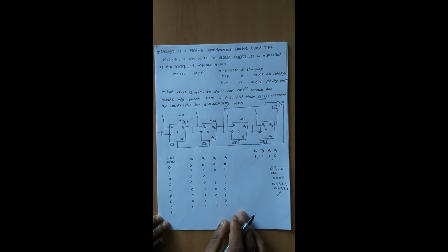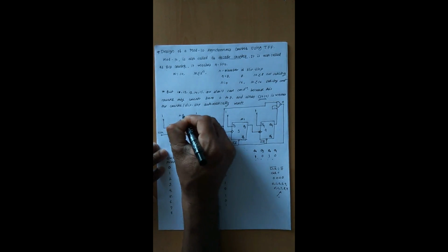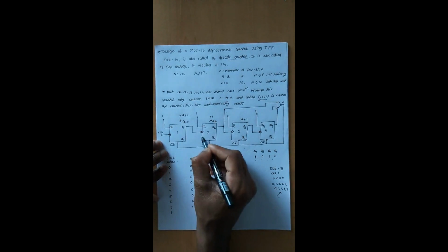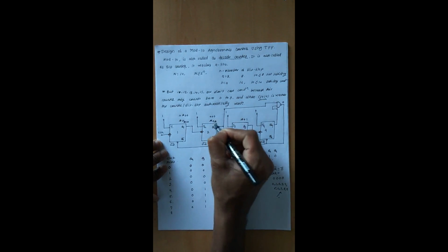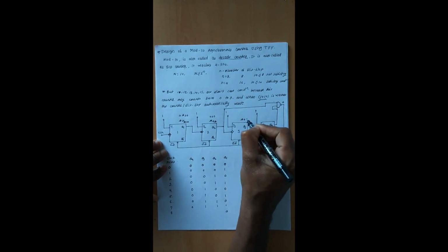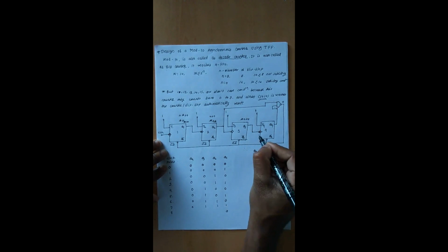For the 8, what will happen? For the 8, this will be 1, this is also 1, this is also 1. Okay, when the 8th clock is applied, then this will be 0, it toggles to 0. Okay, the 0 is applied here, which is 1. Due to this flip flop 2 is set, this again toggles to 0. This 0 is applied here, which is converted into 1. Again flip flop 3 toggles to 0, and this 0 is going here, and due to this the bubble makes a flip flop on, and flip flop 4 will be on, and the remaining flip flops are 0 0.